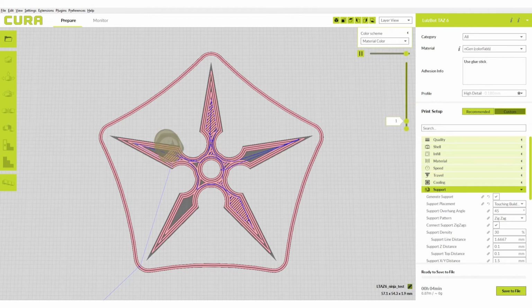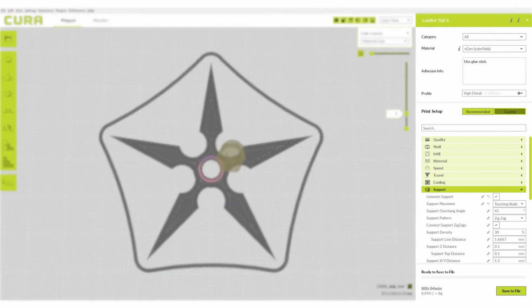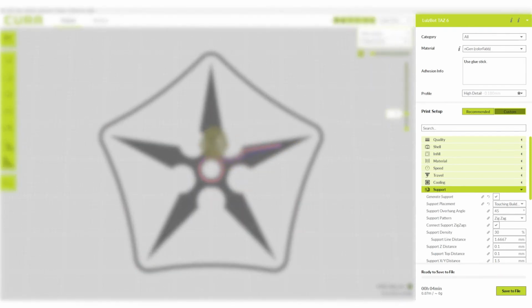This makes sense. The filament has a diameter and changes shape as it cools. As a result, a reconstruction from the printer movements alone is going to be smaller than the original by that same offset. There are multiple other slicer settings that handle physical deformation of the print, which would have to be accounted for to achieve a more accurate reconstruction.